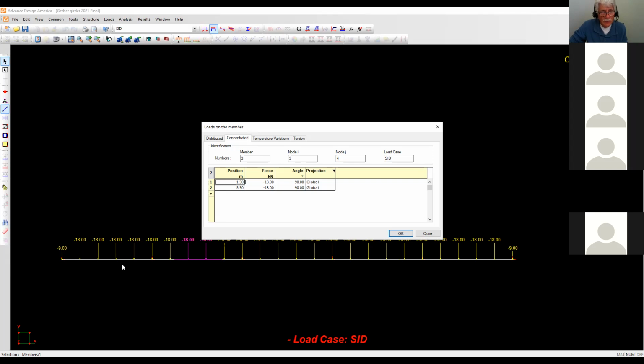For example, I had to work out the length of these members and where this node was on a piece of paper, so that when I went to put in my nodes, I already had that information. Even with software, there are calculations you have to do beforehand so that you know what to input into the program.